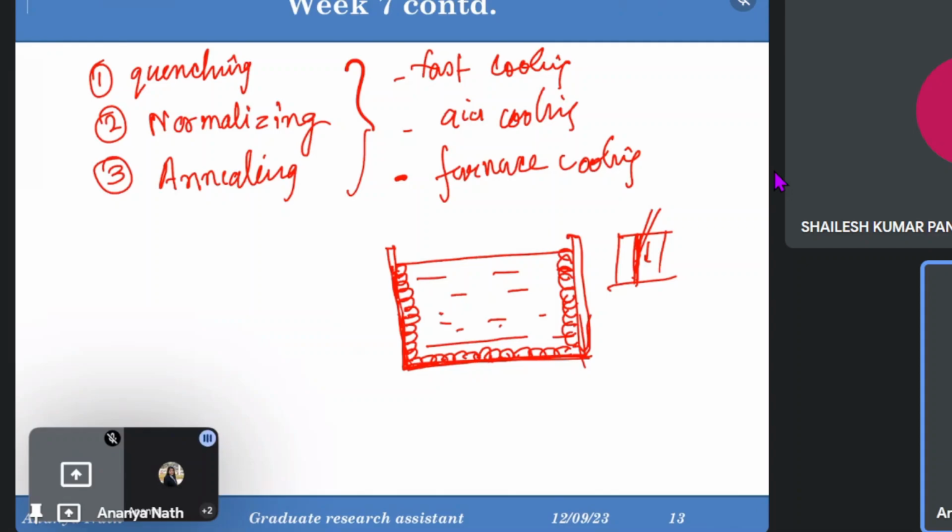But inside this metal, there will be a temperature gradient. As it solidifies, the temperature of this region and of that region will be different, so there will be a temperature gradient. So the grains you get after solidification will have different structures. Somewhere you'll get columnar grains, somewhere equiaxed, somewhere very refined, very small grains. But it's not that they are not nucleating. They have to nucleate, otherwise how could they form the grains?